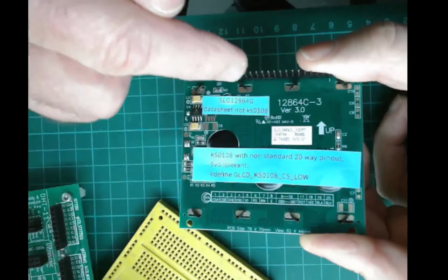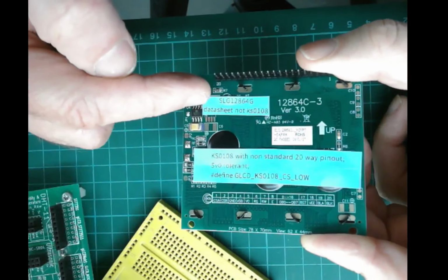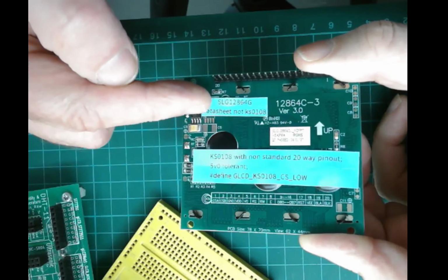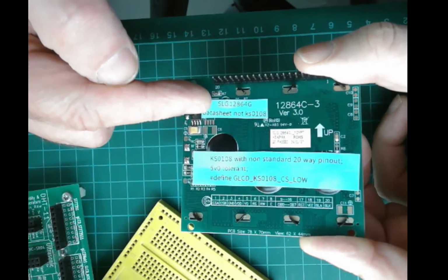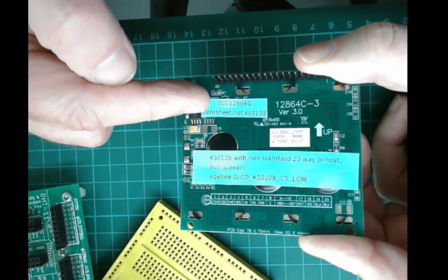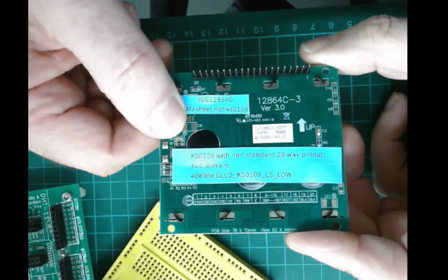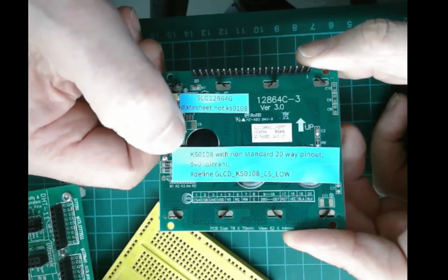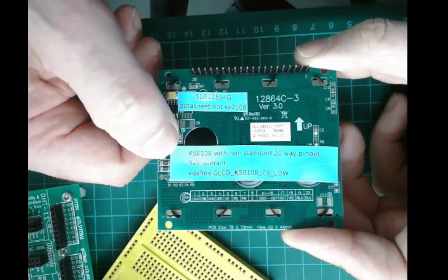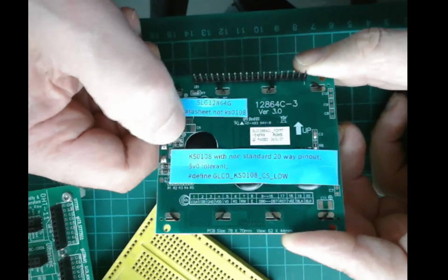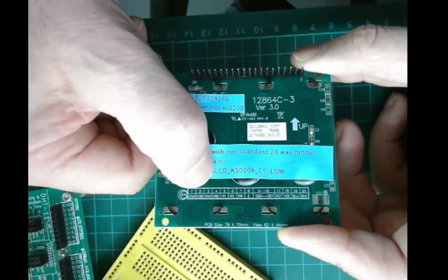As you can see, I've written on here SLG12864G datasheet. Use the datasheet. It's not a KS0108. It's very similar, but it's not the same. And what's the giveaway on here? The giveaway is that there's a non-standard 20-way pinout. It is 5-volt tolerant, and you have to now put in the compiler GLCD